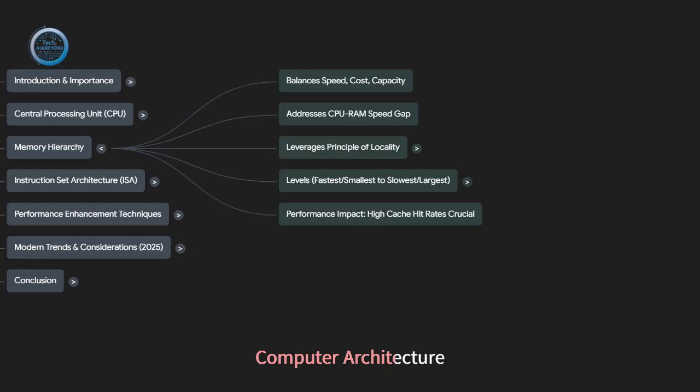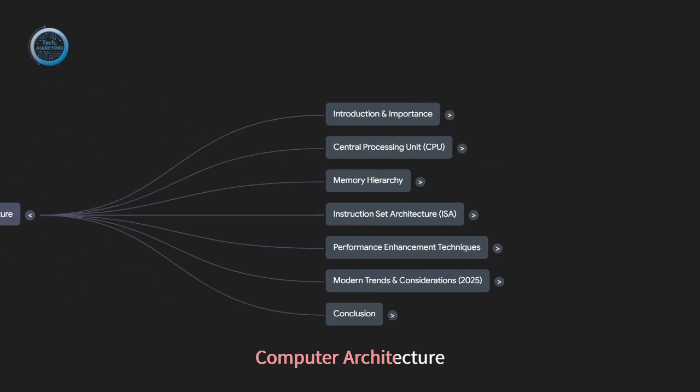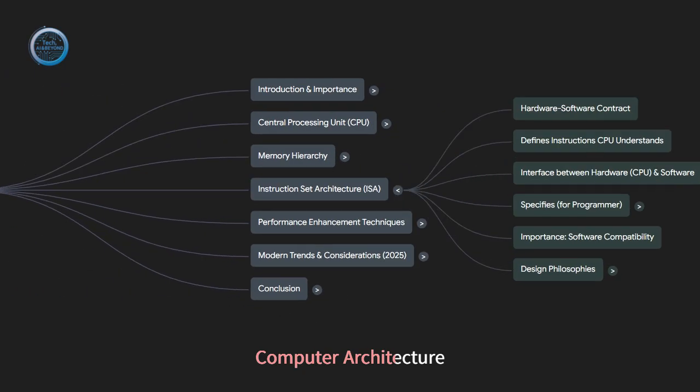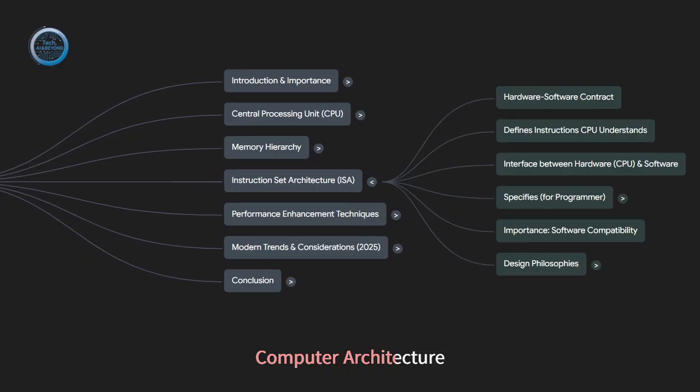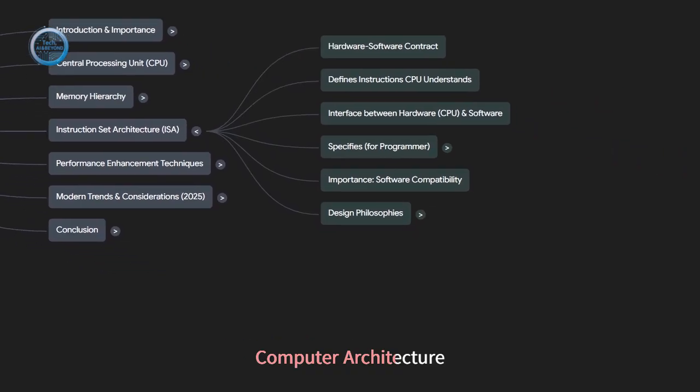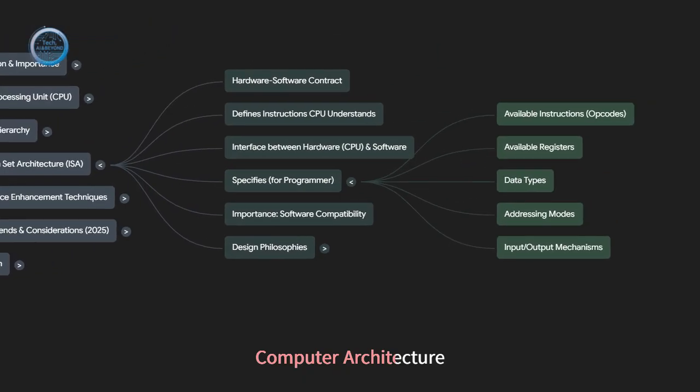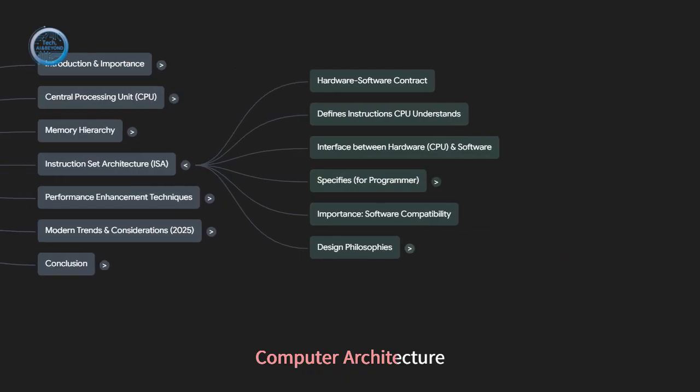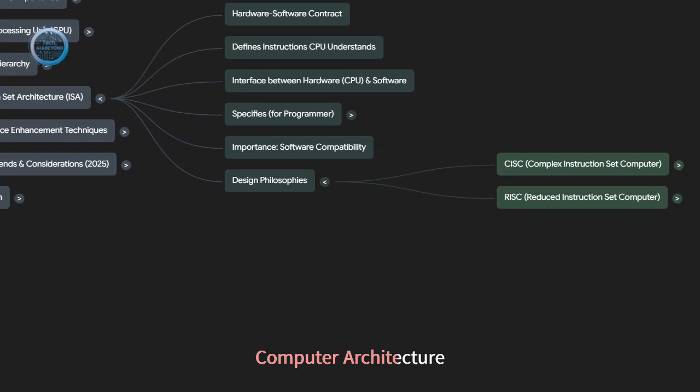Essentially, yes. Each core can run a separate program, or more commonly, a separate thread of execution from the same program, truly simultaneously. This became the main way to increase performance over the last, say, 15 years or so, because pushing single core clock speeds much higher hit the power wall. The power wall. Yeah, running single cores faster and faster generated too much heat and used too much power.